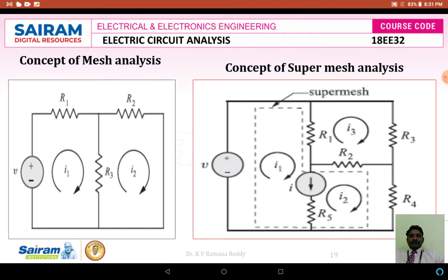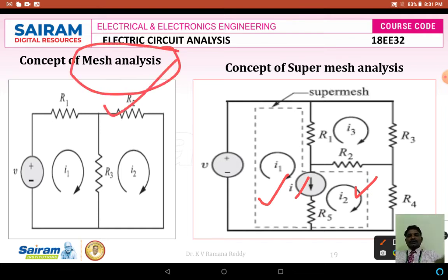Now for these three meshes, with the three currents I1, I2 and I3, if you look closely at this circuit, it has mutual resistors. For example, R1 is the mutual resistor for mesh 1 and mesh 3. R2 is the mutual resistor for mesh 3 and mesh 2. Similarly, there is one current source located at the boundary of two meshes, mesh 1 and mesh 2. This is small i. Whenever there is a current source between the boundaries of two loops, it is not possible to use mesh analysis to simplify the circuit and find the unknown loop currents.